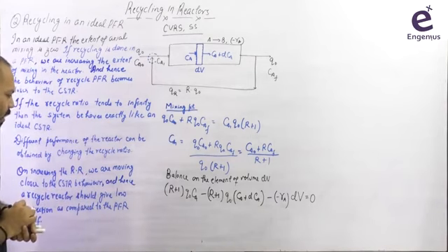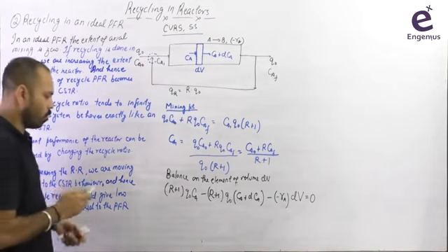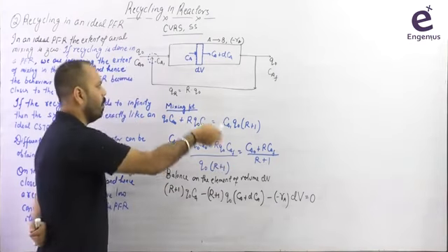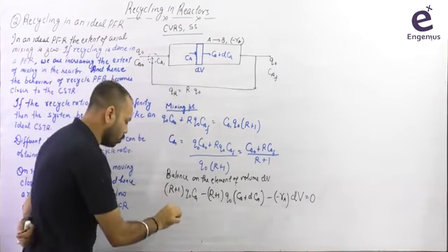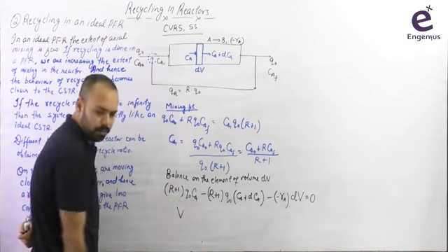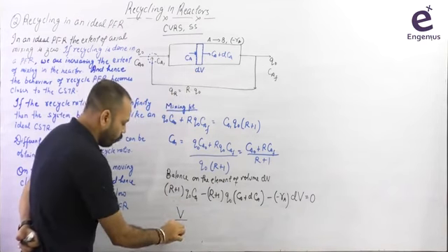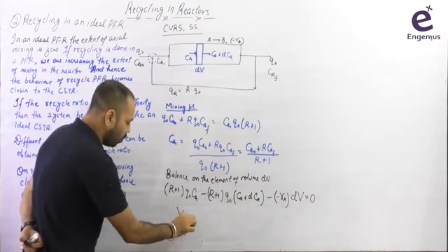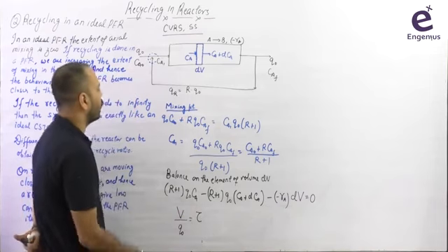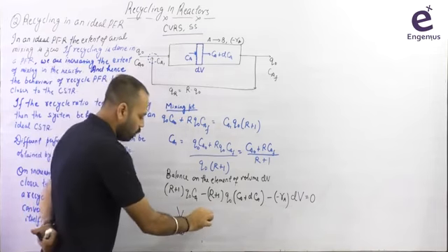A lot of things are getting cancelled here, right? And I hope you'll be able to integrate this equation. After integration, what are you going to get? dV will be integrated from 0 to V, and you are going to get V by Q naught. V by Q naught is equal to tau of this reactor with respect to this volumetric flow rate.